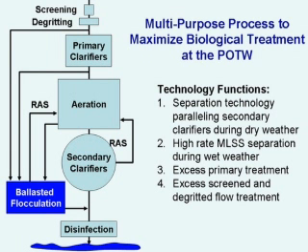There are systems that have been used to keep the chemical mixed so that it does not stratify and have variable potency throughout its depth. And then another issue is the ability to test the actual concentration of the stored chemical so that you know what you're dosing. Because if you can keep tabs on what the potency of the chemical is, then you can potentially adjust your feed rates, if you have a SCADA system, for example, that operates that disinfection feed system, then you can up your application rate in order to account for some loss in potency.